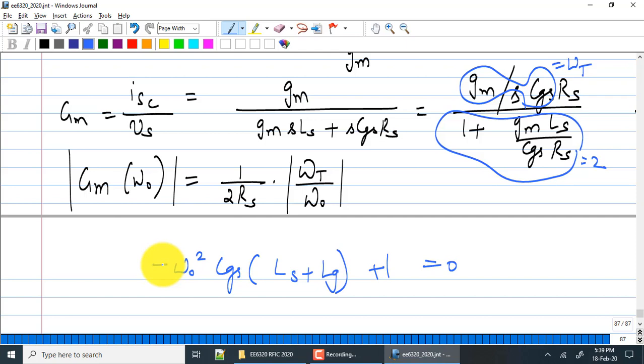Okay, but what this tells you is if you were to keep omega t constant, how do you do that? By scaling the device and the current together. That is how you keep omega t constant. Right? If you were to do that, you can see that the effective overall transconductance of the device stays the same. Okay? Remember earlier we wrote it in terms of Q in etc. Okay? So Q in itself is a function of the operating frequency that had some frequency dependence inside.